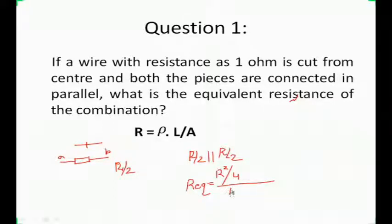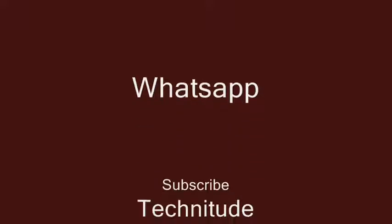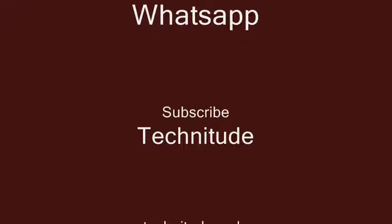The product of the two resistances is R square by 4, so R equivalent would be equal to product of the two resistances upon summation of the two resistances, which is R. So from here this R cancels out from the square and equivalent resistance becomes R by 4. If two equal resistances are connected in parallel, the equivalent resistance becomes half of that, and as we have taken only half the resistance and connected into parallel, that's why the resistance has become R by 4.